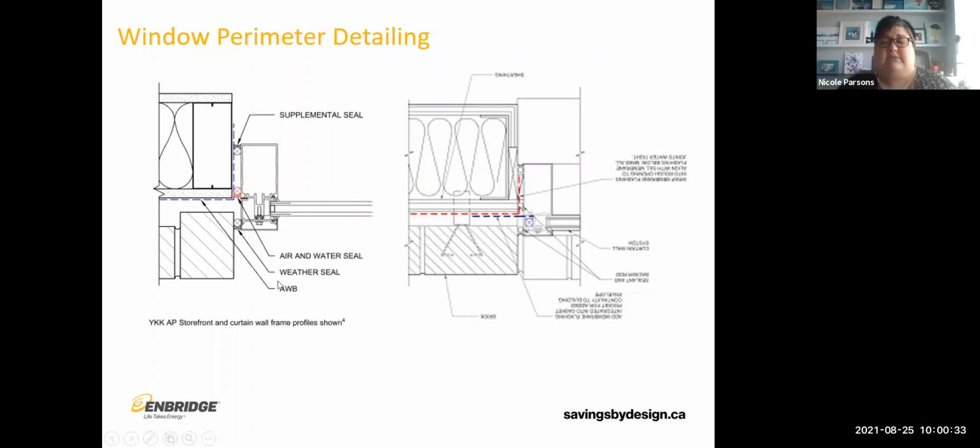So these sections are curtain wall sections, just for comparison. The wall sections beside the curtain wall are very poor thermal performance. You can see that they have insulation inside the stud space, but there's nothing outside behind the brick cladding. Alex will talk more about why that is not a great way to build a wall if you're trying to get an energy efficient building. I'll talk more about that this afternoon.